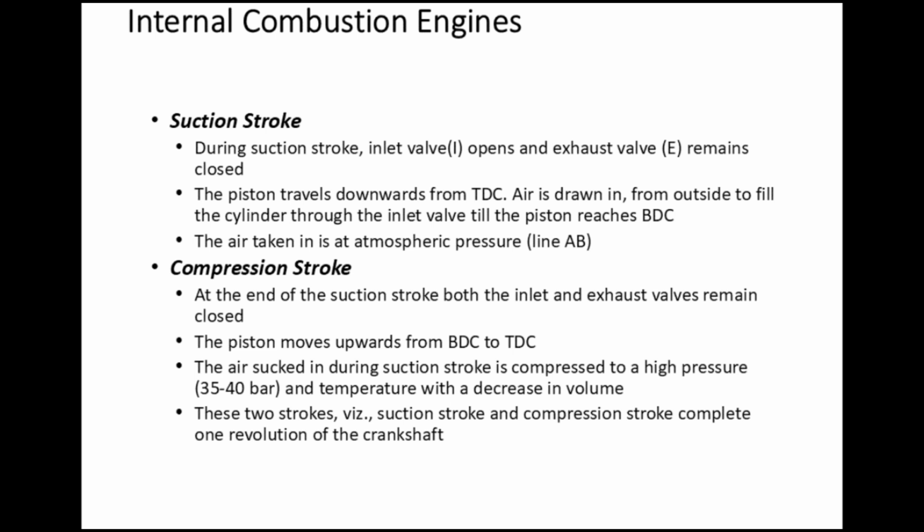Compression stroke. At the end of the suction stroke, both the inlet and exhaust valves remain closed. The piston moves upwards from BDC to TDC. The air sucked in during the suction stroke is compressed to a high pressure of 35 to 40 bar and high temperature, with a decrease in volume. These two strokes, namely suction stroke and compression stroke, complete one revolution of the crankshaft.